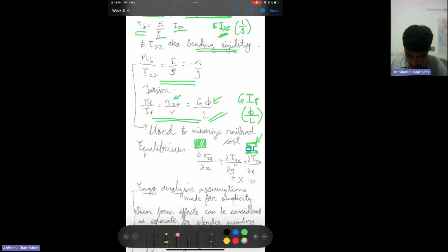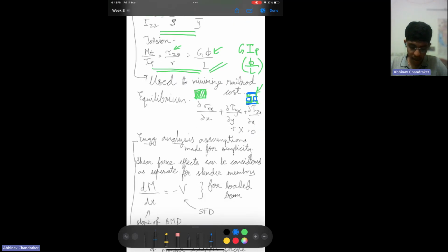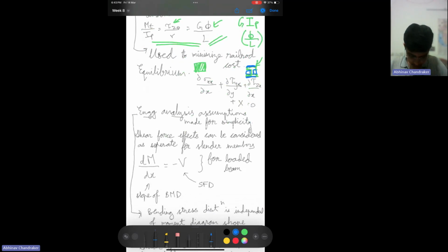So from here you have removed some material, but still being able to retain most of the bending rigidity because the moment of inertia is higher since you have material at farther distances. Moment of inertia will have greater contribution from material which is farther than from one which is closer to the center. So that was the idea why we have these kinds of railroads.